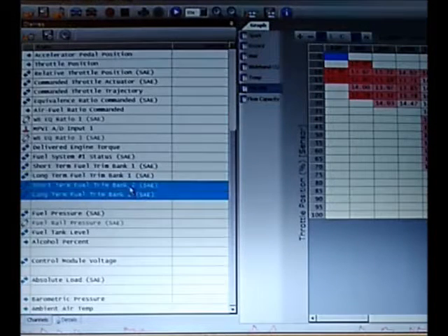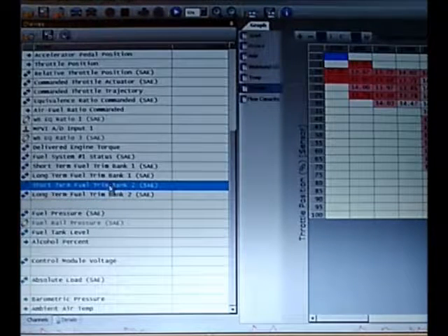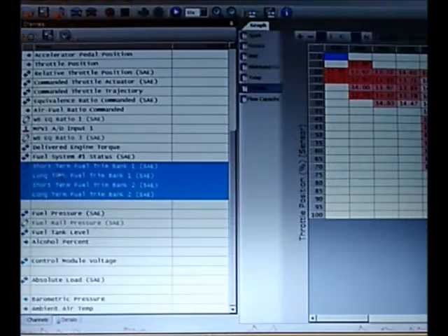That's kind of like novice level tuning. That's where everyone starts, and that's where I started, and it's good for a while, but eventually you demand more from your car, and you're going to have to abandon this altogether and just go with open loop tuning, which doesn't use this stuff at all, because this is based on your built-in O2 sensors, and we've just turned all that stuff off.